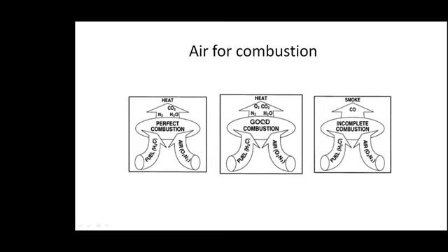That extra air takes a lot of heat out of the chimney. So optimization of the air is a first fundamental principle in energy conservation in thermal utilities. When there's a fuel, what is the amount of air that is required? Stoichiometric. Over and above the stoichiometric, we give some more air to ensure complete combustion.